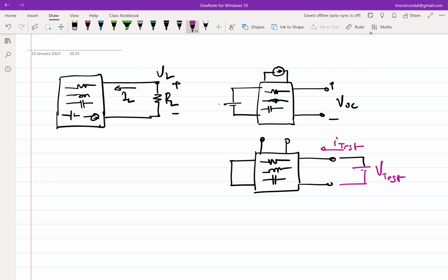Yeah, any voltage source. Is the impedance. Why is that right? Okay. He is asking how. Okay. So when I am saying that I can find out an impedance, I am implying there is an impedance, right? So if you agree with the fact that there is an impedance, let's say it's called Z, then I can replace whatever is looking in with an element which is Z, right? So now the question is, how do I find Z experimentally?